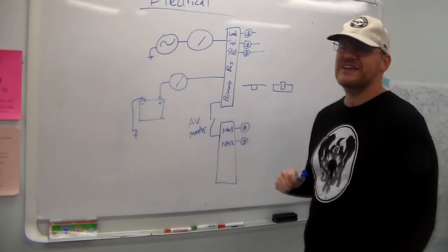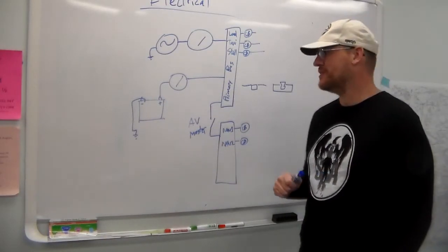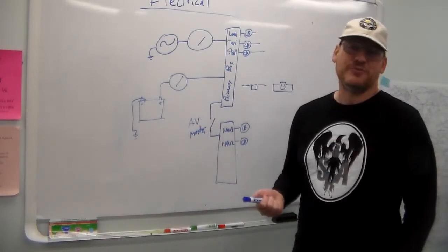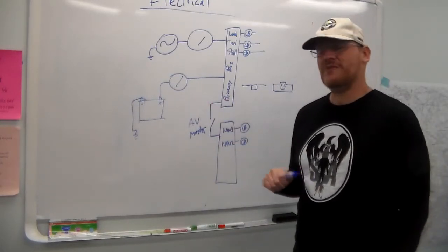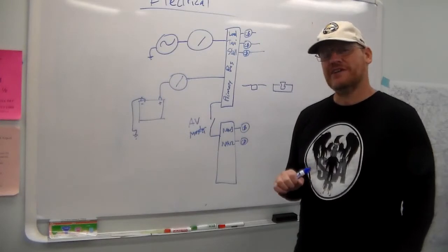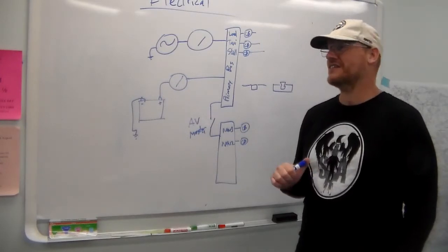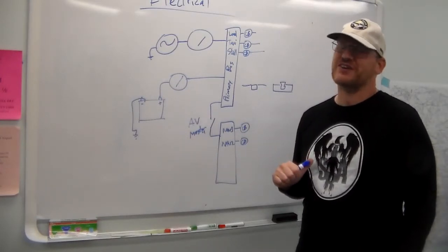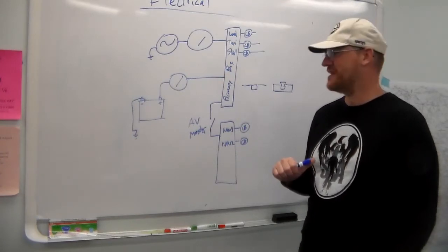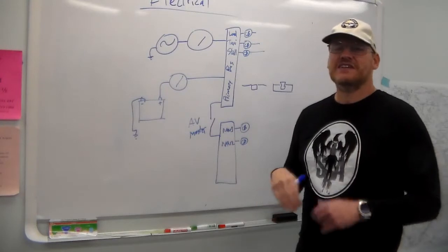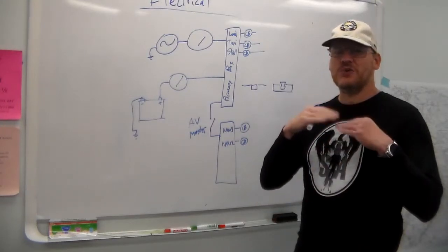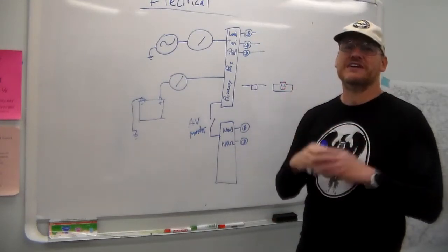Speaking of wiring, another little tidbit for you, in case you ever, I don't know, built a plane or something. When you buy wire, you can buy solid wire, you can buy stranded wire. Solid wire is not permitted in aircraft. And the reason for that is that if it vibrates, it can flex and it can cold work and then break.